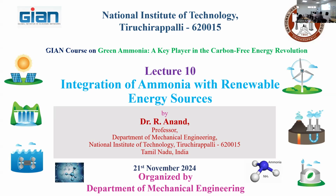We are going to reduce the pressure. Assume that here the pressure is P1 and there it is P2. So we are going to drop the pressure from P1 to P2. By doing so, the volume increases, the pressure drops, and work is produced. As you all know, work is specific volume times delta P: the specific volume of the fluid entering, and how much the pressure drops. So if delta P is more, we will get more power from the turbine. That power is converted to electricity by connecting a suitable alternator.